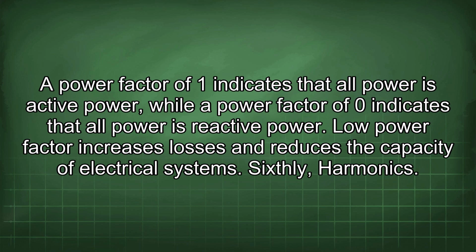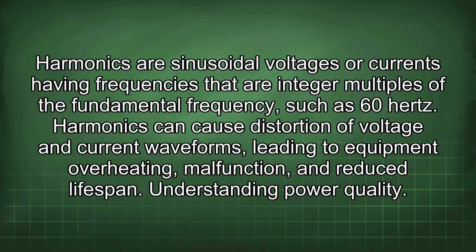Sixthly, harmonics. Harmonics are sinusoidal voltages or currents having frequencies that are integer multiples of the fundamental frequency, such as 60 Hz. Harmonics can cause distortion of voltage and current waveforms, leading to equipment overheating, malfunction, and reduced lifespan.